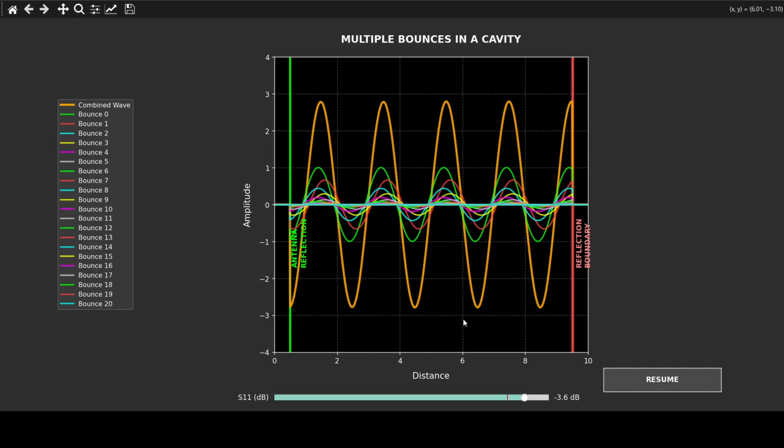And one other major thing here is the power transfer, meaning that when you have an impedance mismatch, assume that your input has an impedance of 50 ohm, but your receiver has an impedance of 100 ohm. If you assume there is a voltage division here, compared to when the input of the receiver is 50 ohm, if it's 100 ohm, definitely the amplitude becomes higher because more of that voltage division comes to the receiver.